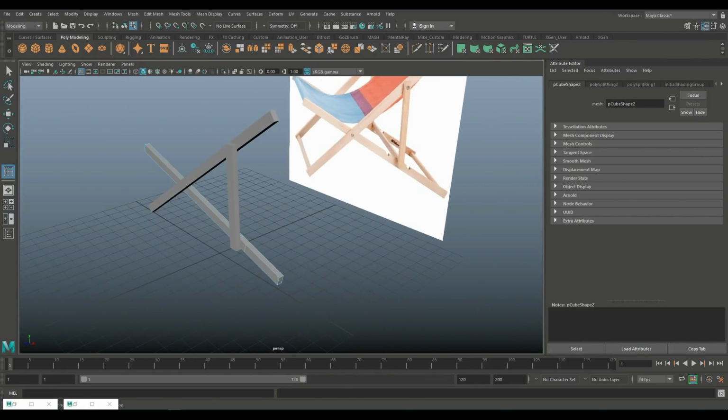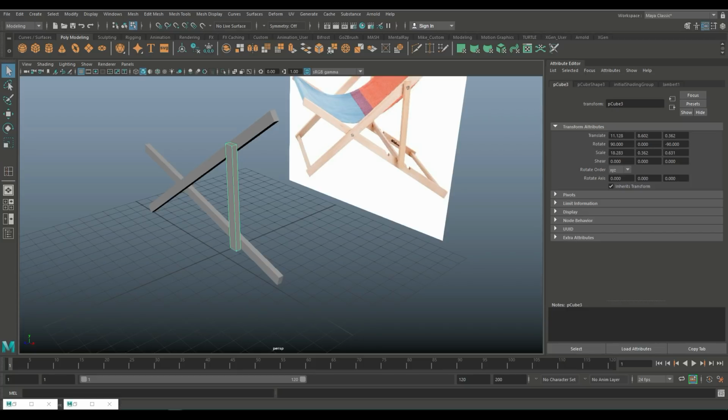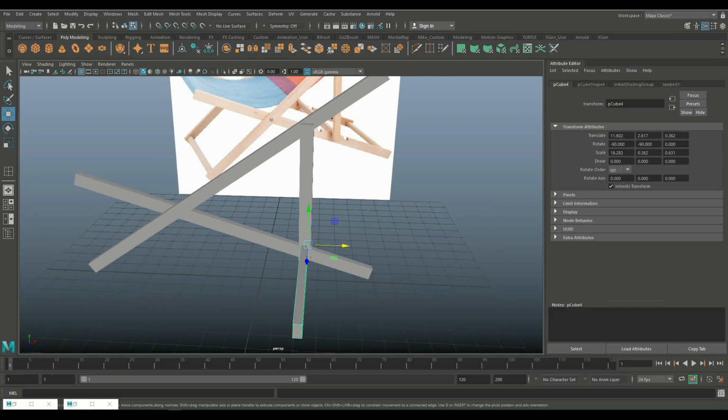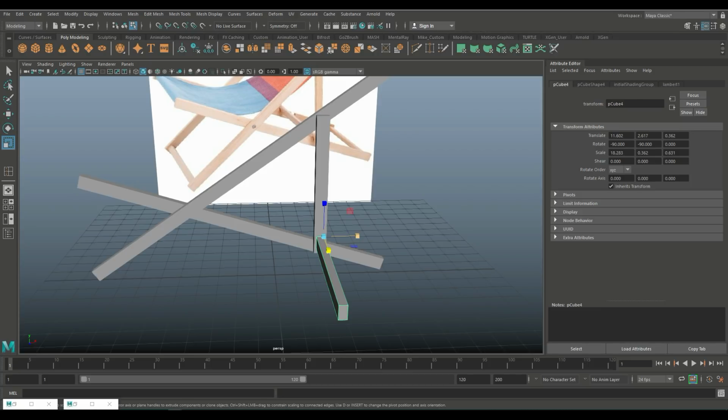And the best way to find out is just to take this, Control D to duplicate, E to rotate, hold down J, and then we're going to flip it down again until it's basically upright, like so. We're going to W, we're going to move that down, we're going to move that in here. This can be a bit thinner, so we'll hit R and we'll bring that in like this.